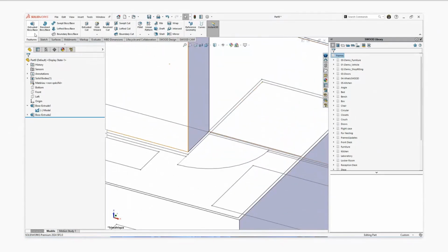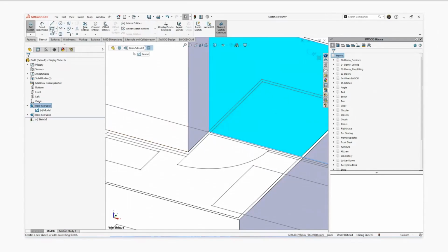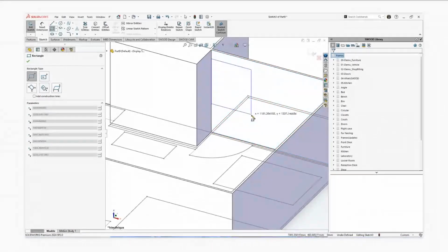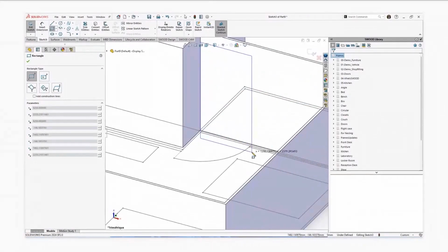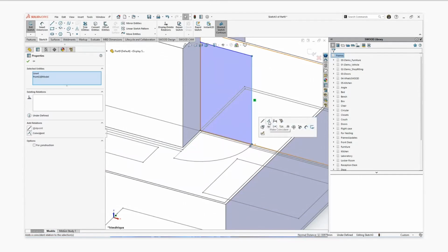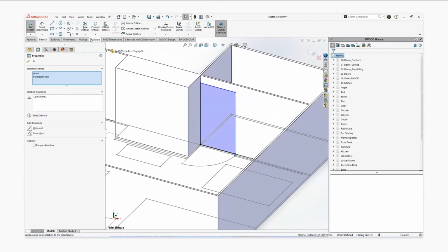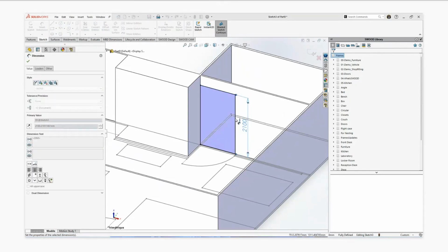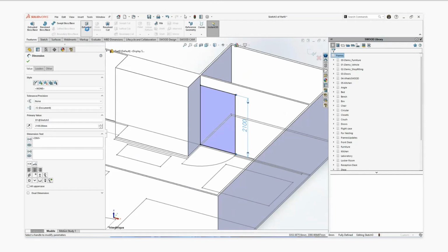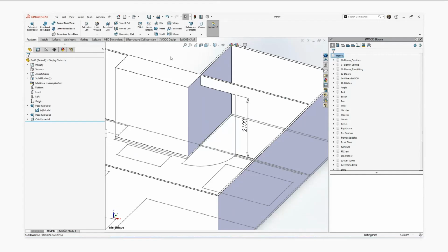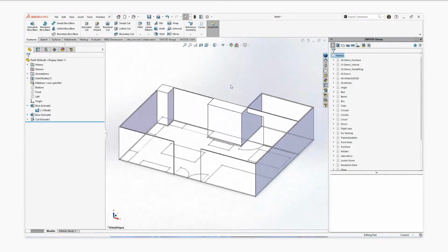Here, as you can see, there is a door. Okay, that's good. I want to create a door. I just have to create a rectangle on this wall. And then this rectangle, I will link it to the DXF I already imported. And from this shape, again, instead of creating a volume, I just want to remove this volume. So here I create a dimension, because that's the power of SolidWorks. You create any kind of dimension, and at any moment you will be able to change these dimensions. That's why SolidWorks is a parametric software.